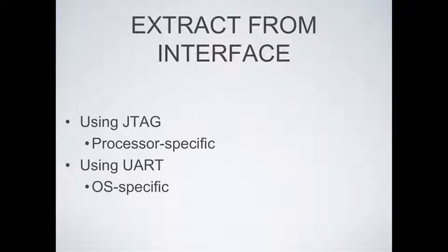And what you have to do at that point is extract from the interface. The reason why you want to extract from the interface is that at some point in the boot sequence, the system or the bootloader is going to read the data out of that non-volatile space where it's been encrypted. It has to decrypt it and then store it into RAM, and then inside RAM it'll be able to execute the data in plain text essentially.